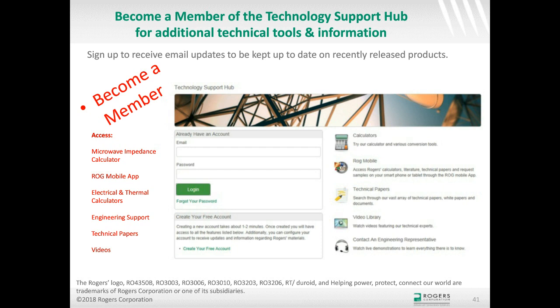Acrylic's a little bit better than epoxy base. Blue might be a hair better than the other colors. And if you had a thinner, consistent solder mask, that's going to be better, but the consistent thickness would be the trick there. So I guess I really don't have that good of an answer for the solder mask question.